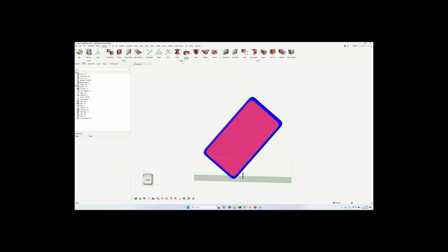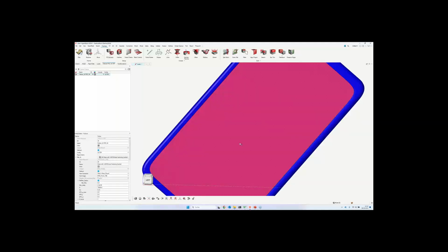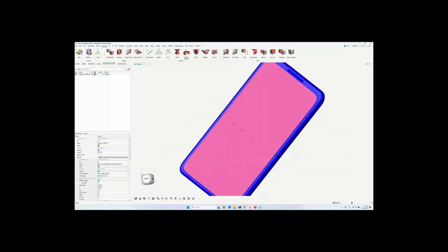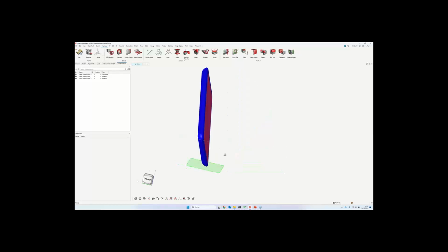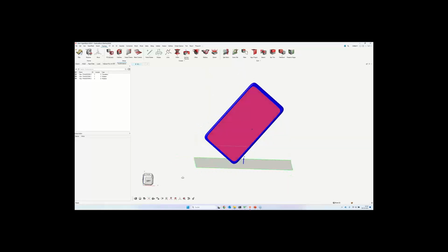Now maybe more interesting features like the material models for this cell phone, using an elastoplastic piecewise linear model. In addition to failure criteria, here I'm using the failure criteria for this tempered or Gorilla Glass, which uses a special failure criteria to model the fracture of this tempered glass. So I have transformation cards to do the automated reorientation of the model, because if I want to have DOE studies or whatever stochastic analysis, I can do it automatically in the solver.